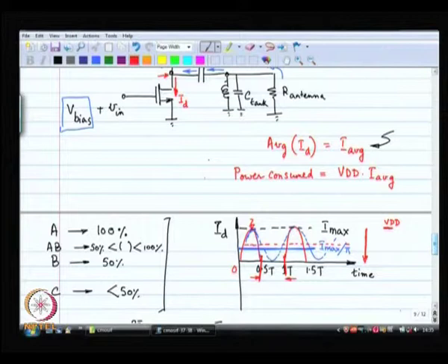when the current is the largest, the voltage over here will be the smallest, right. You can't allow the voltage over there to go below the saturation voltage of the transistor. Now, we made an assumption in the last class, and let us say that the minimum saturation voltage that you possibly can have is 0 volts. All right, this was a bad assumption, but nevertheless we are using this assumption for our analysis, because otherwise it is overly complicated. So, therefore, what I am trying to suggest is that at this point of time, the signal voltage should be VDD, right, which means I max times R has got to be equal to VDD. That is my argument.